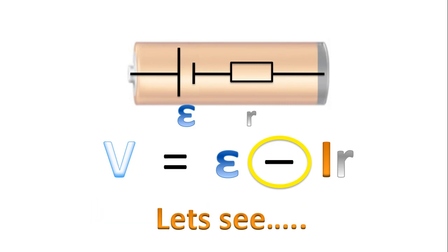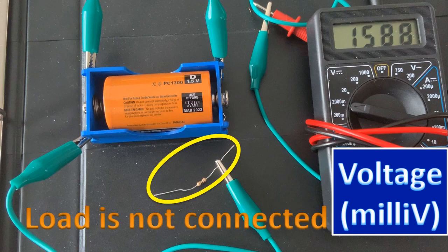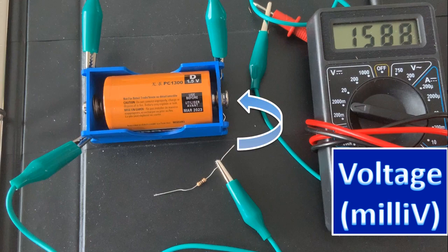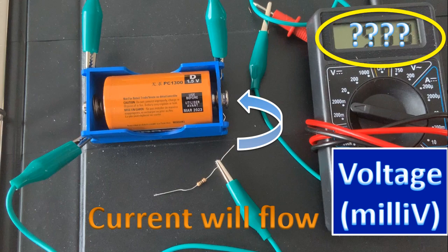Let's see. So initially, we've set up our circuit so that the current is zero. It's zero because the load is not connected. Notice our reading of voltage, 1588 millivolts. So in a moment, I'm going to connect the load to the battery. Current will begin to flow. And the question is, what happens to the terminal voltage?